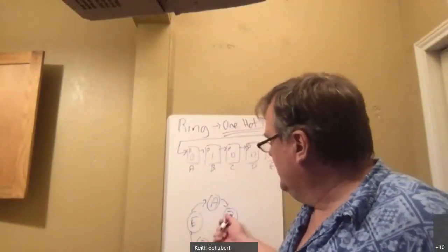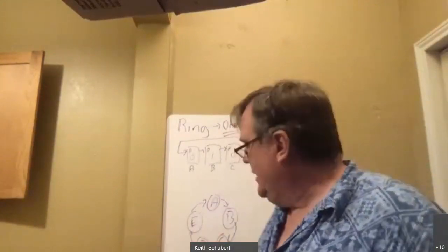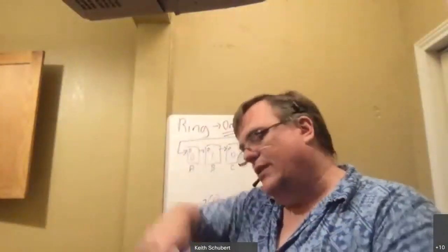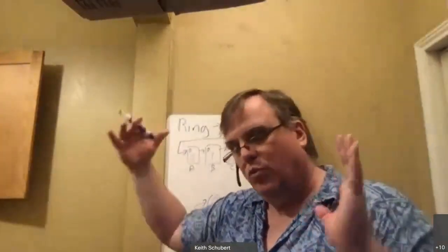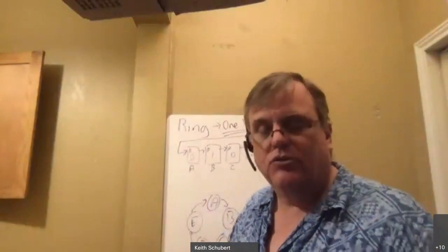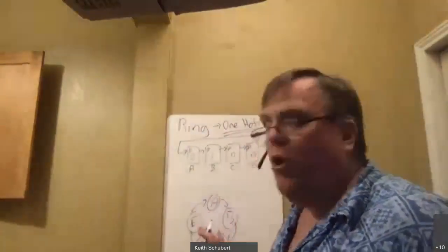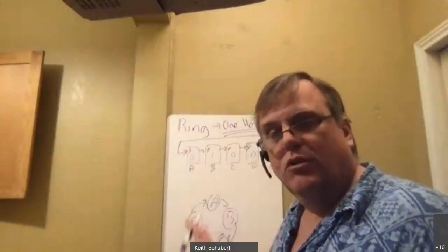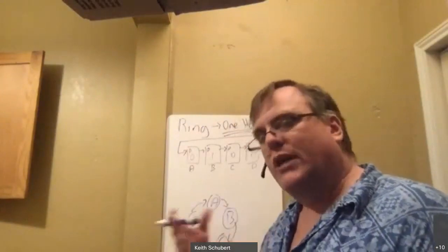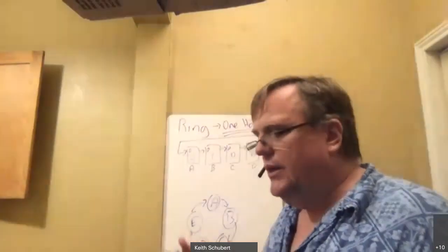Inside each one of these, when you decode it, you'll split to different states depending on what the command is, and we'll show different ways we can handle this. If you drew it out in all of its glory and built it in one big swoop, you'd have a giant number of states, easily thousands of them for different commands. But you can also break them up into smaller pieces, which makes it easier. This fits nicely for that type of sequence as long as you break them up. Worst case scenario would be a huge number like that if you did all the instructions separately.